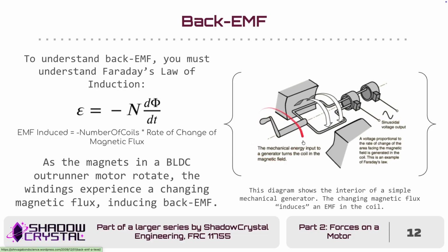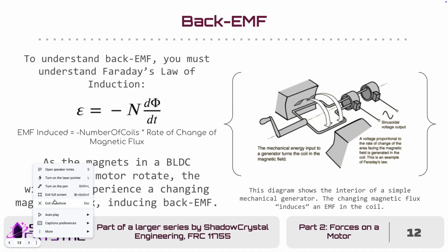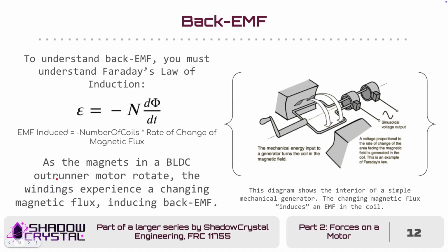If you were to turn this crank faster, almost jumped the gun a little bit. So before I get into that, Faraday's law of induction, do pardon me. So this symbol here is equivalent to the EMF induced. That's your back EMF. It is equal to the number of coils, or in this case windings, times the rate of change of your magnetic flux.